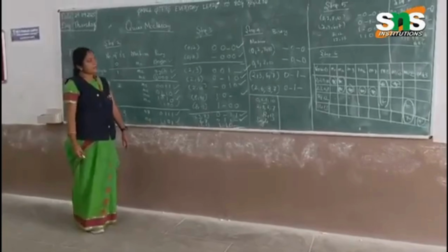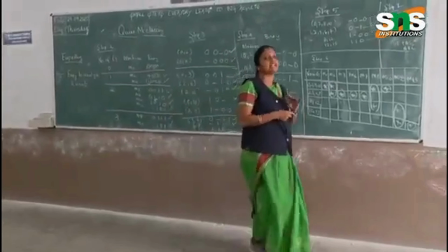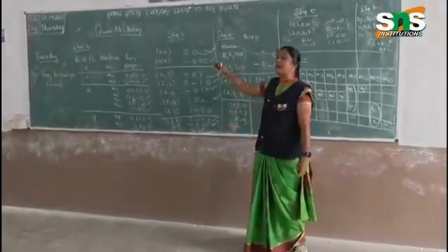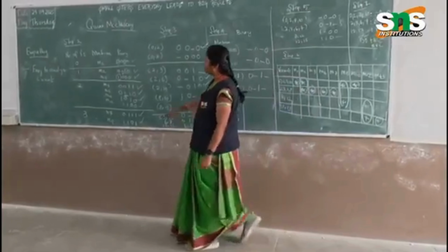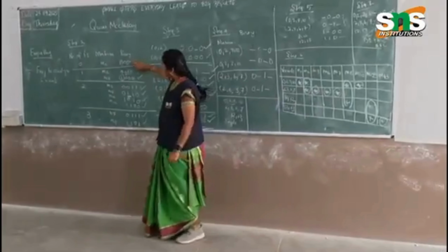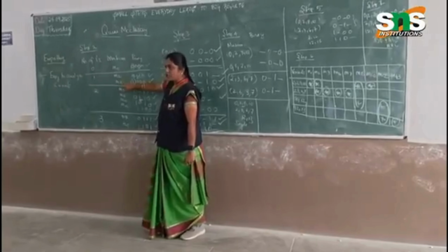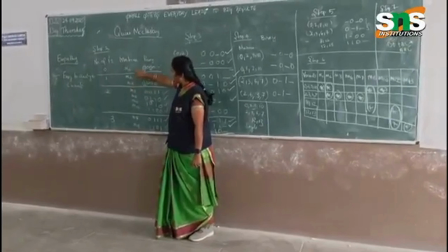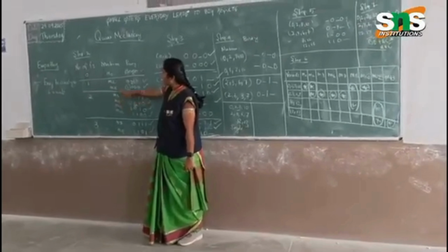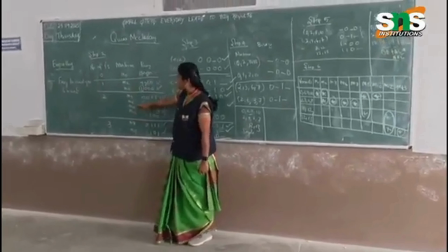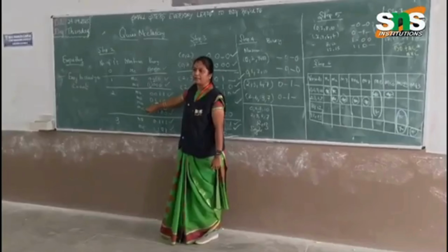The next step is to combine and compare the minterms with the adjacent higher orders. First we compare the zero-ones group with the next one. In the first group there is only one minterm, and in the second group there are 2 minterms, 2 and 8. So we compare m0 with m2 and m8. Then we compare m2 and m8 with m3, m6, m10 and m12.